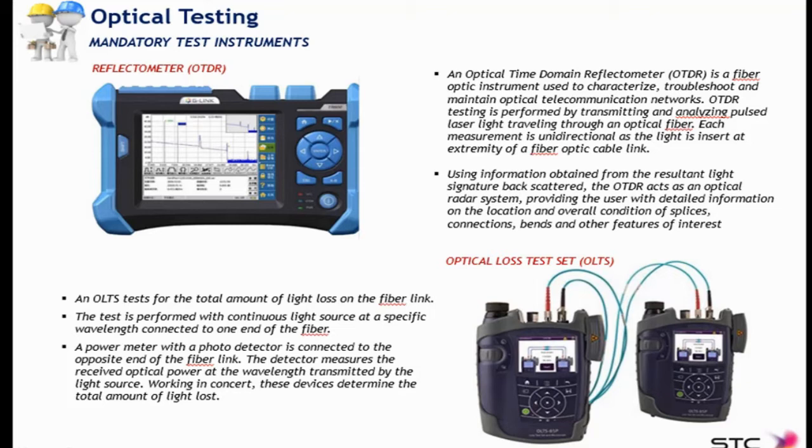The OTDR is an optical time domain reflectometer used to characterize and troubleshoot fiber networks. The OTDR works by injecting a pulse of light at a predetermined wavelength and width, so pulse duration, and measuring the backscatter light.